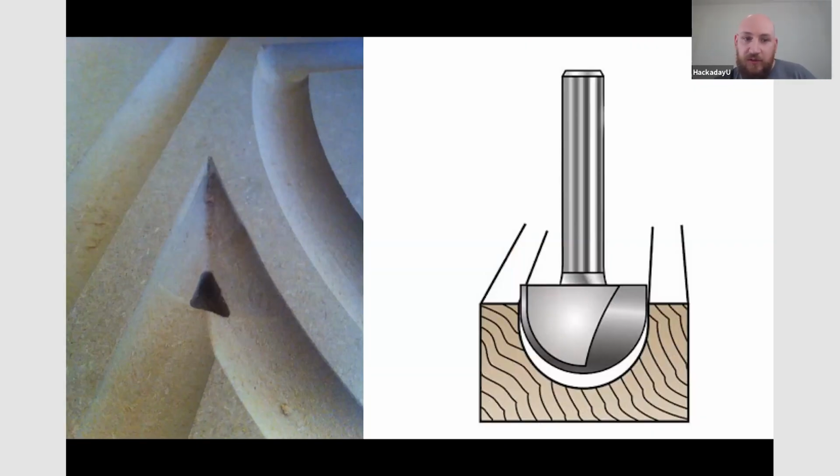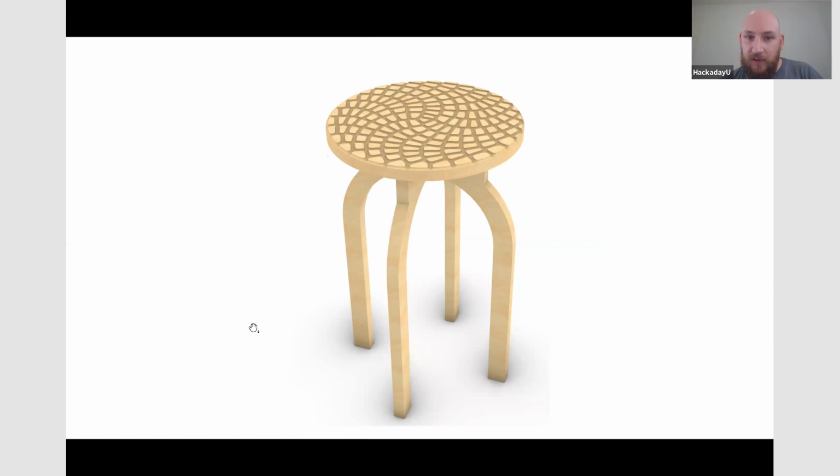And one of the tools I'm going to use, indicatively, in my design is a bullnose router bit. In controlling any router bits from Rhino, I'm just going to have profile curves, and when you export it, you would assign this router bit to go along that curve. So I just really need the mid curves. This is an example of using a router bit like that there. And this is kind of what I'm going to draw.